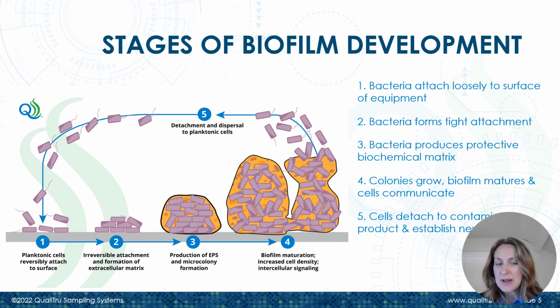Especially when you have cracks or pinholes, but it can also just be that polished stainless. Over time, it builds a shield, and it will release small bits over time. It could be spores, it could be different types of contaminants into your process. The challenge is that it's not uniform, so it can be difficult to identify where that biofilm is coming from and to know exactly how it's going to impact your product quality.